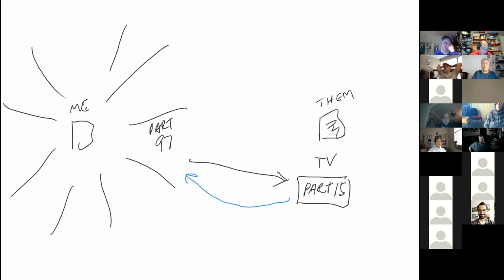So, what might be a problem if you report that an audio signal through a repeater is distorted or unintelligible? Well, there's a couple of reasons why you could be unintelligible. If your transmitter is off frequency, FM sounds really bad. Your batteries could be running low. You can also be in a bad spot, and thus your signal is very weak. Or you could have RF feedback.